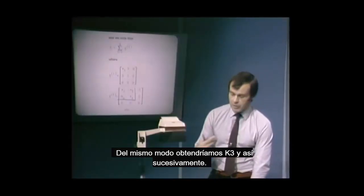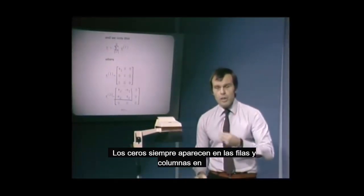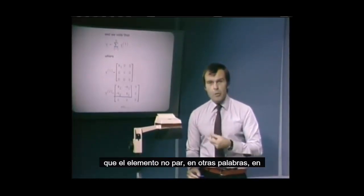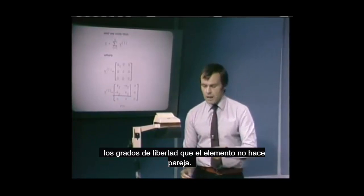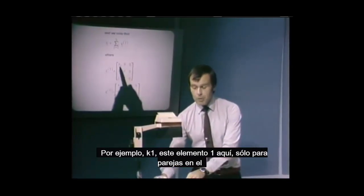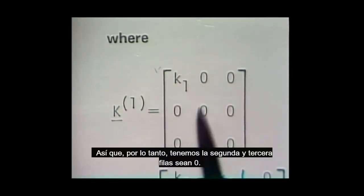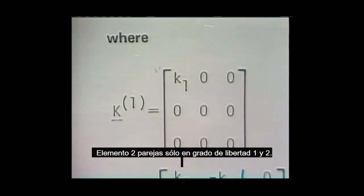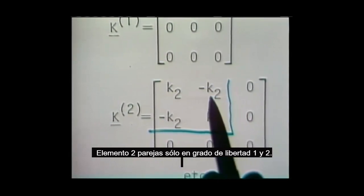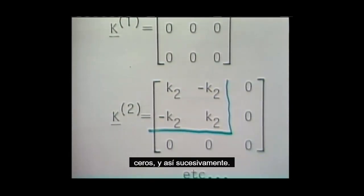Similarly, we would obtain K3 and so on. The zeros always appear in those rows and columns into which the element does not couple. In other words, into those degrees of freedom that the element does not couple. For example, element 1 here couples only into degree of freedom 1, so the second and third rows are 0. Element 2 couples only into degrees of freedom 1 and 2. Therefore the third degree of freedom contains all zeros, and so on.